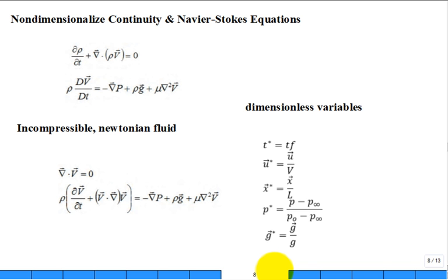So you go back to the continuity and the Navier-Stokes. We're going to work with incompressible Newtonian fluid, simplify it as we just have seen, and if you introduce dimensionless variables, the easy one maybe is dimensionless velocity. So you take your velocity vector everywhere and you just divide by cap V. What is cap V? Maybe that's the approach velocity incident on my object that I'm studying in the wind tunnel. Cast the lengths. Each dimension is normalized by one length scale.